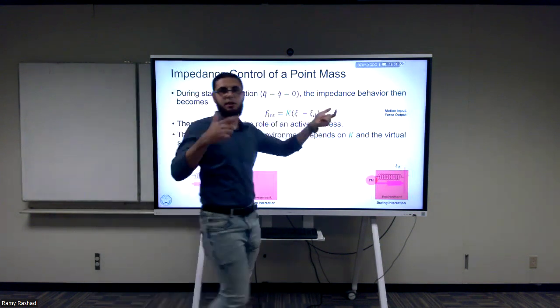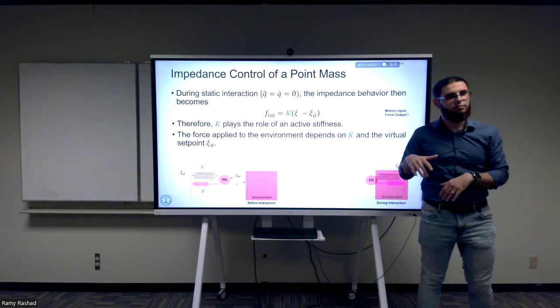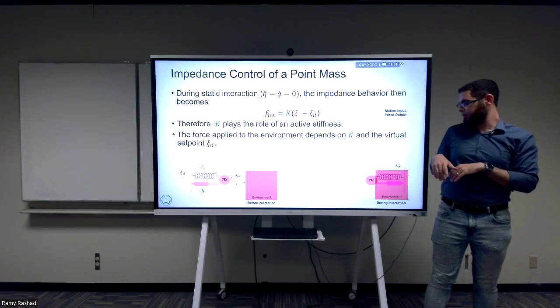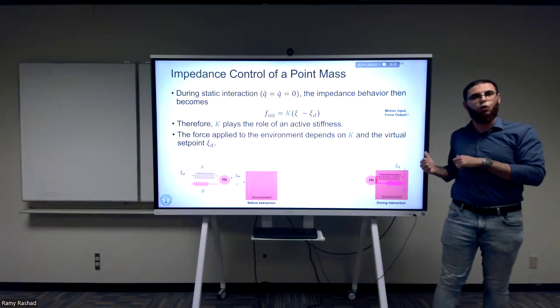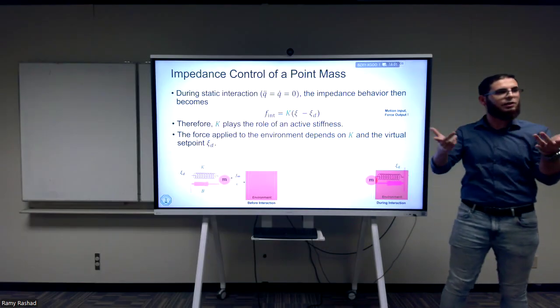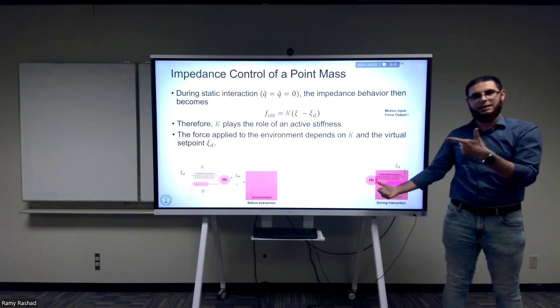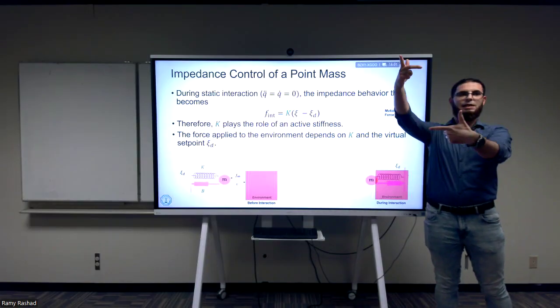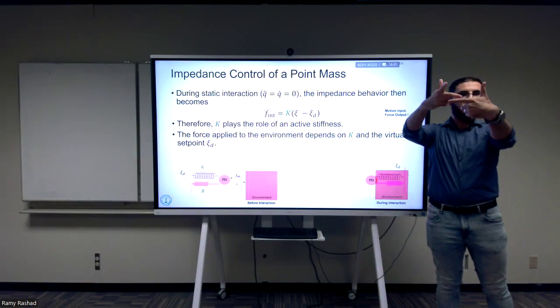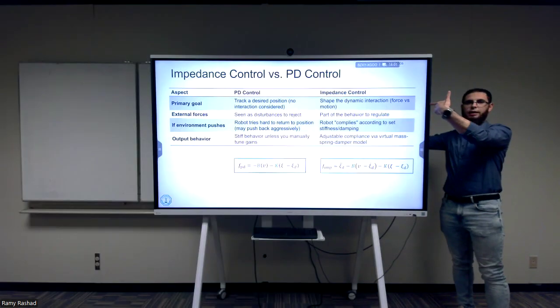So psi minus psi desired, they have to be, okay? Again, depending on the sign, how you define. But the psi desired needs to be inside of the wall, and now you're going to be pushing on the wall. So the scenario of how we do impedance control is that if this is the end effector, in this case just the point mass, and this is the desired frame that I want to go to, I'm going to choose the desired frame to be inside of the wall, and now it will start to interact.